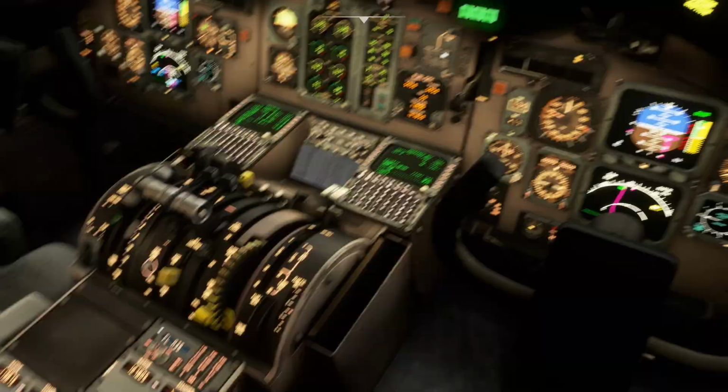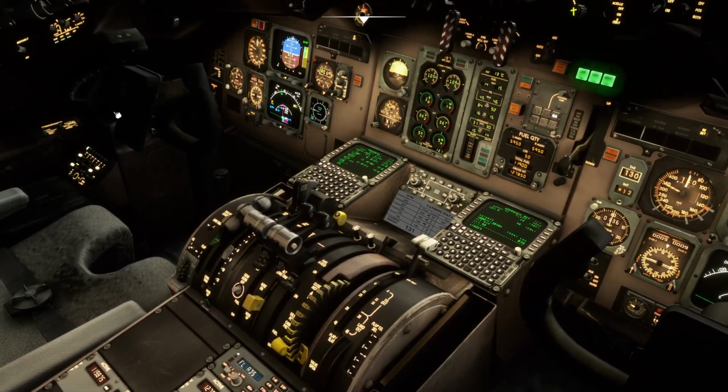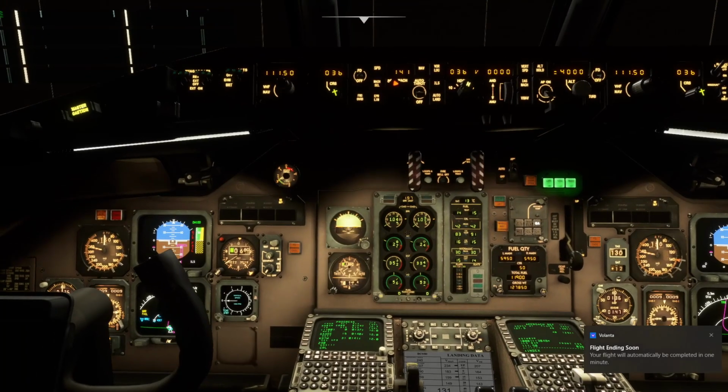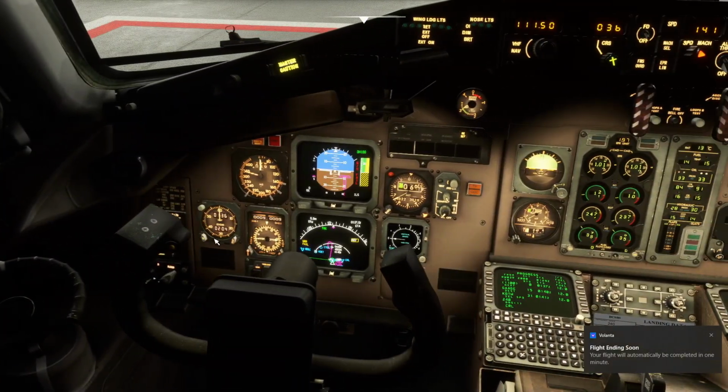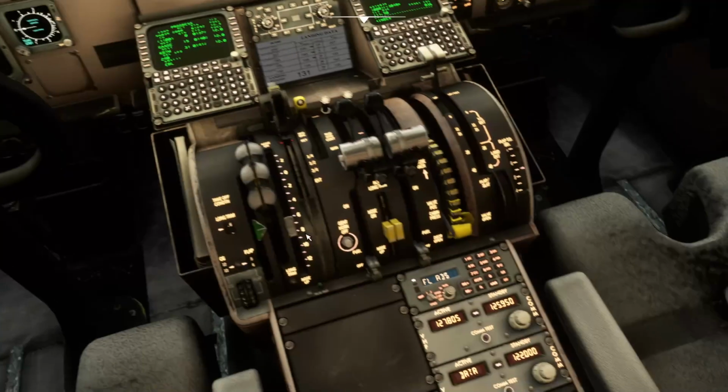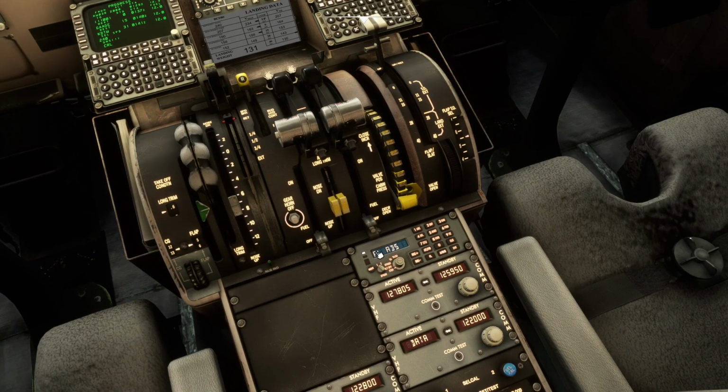Looks good. So, parking brakes are set. We can click the fuel, or we can scroll down on the fuel cutoff switches to shut them off. Thank you, Valanza, for loudly telling me something I already know. We'll stop the block timer. We'll set the transponder to standby.